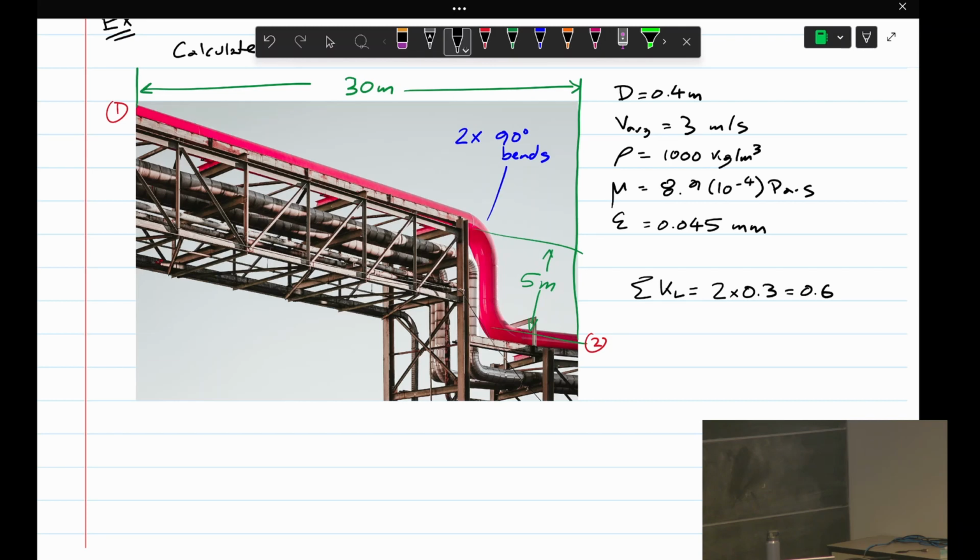That would be for something like a really complicated flow component, or you're designing a valve, or you have a bunch of valves interacting and maybe creating a high velocity region that's spraying on one part of your tank so it could create extra wear. Basically, anytime you're worried about the local flow properties, this analysis breaks down, because this is all about the average velocities, average pressures.